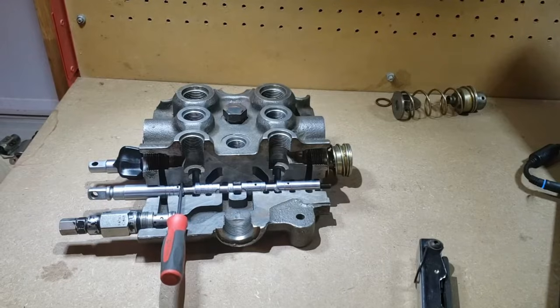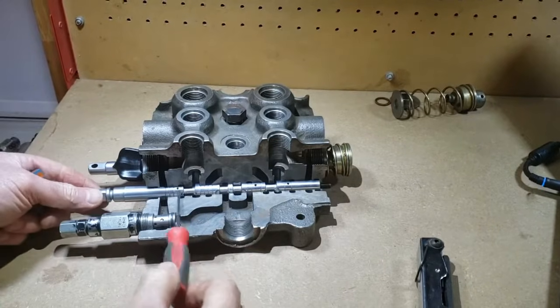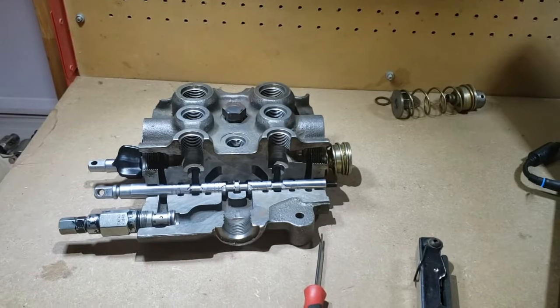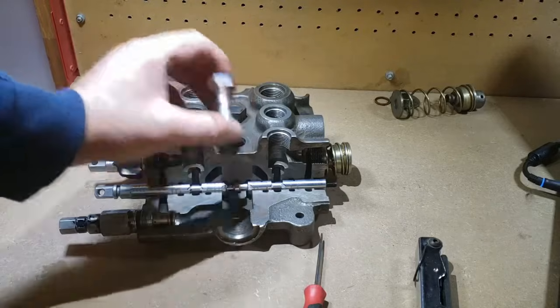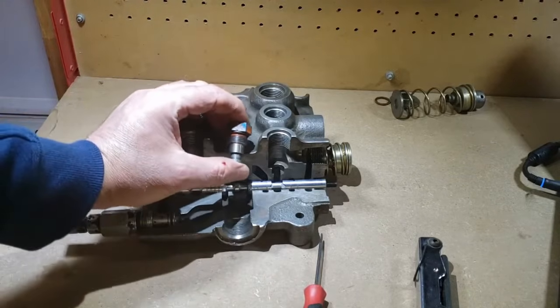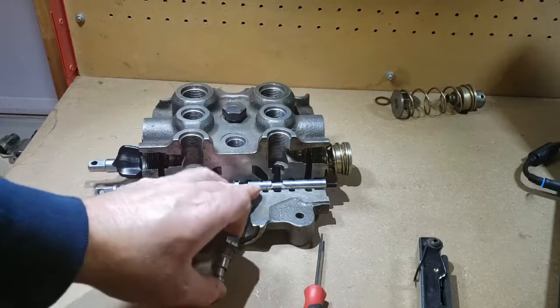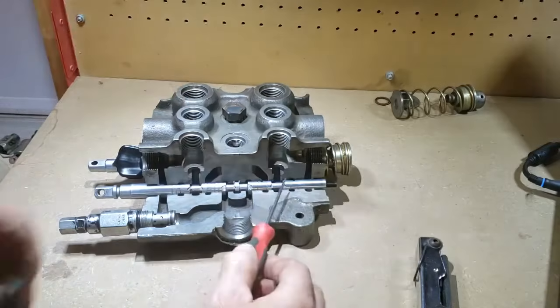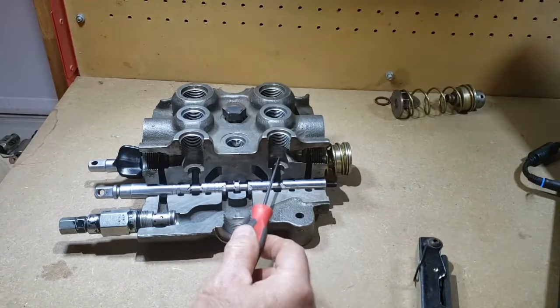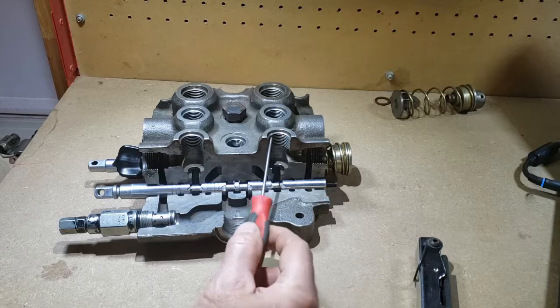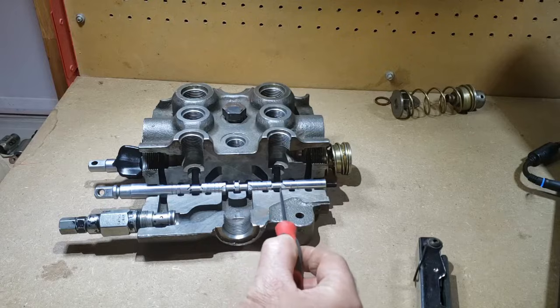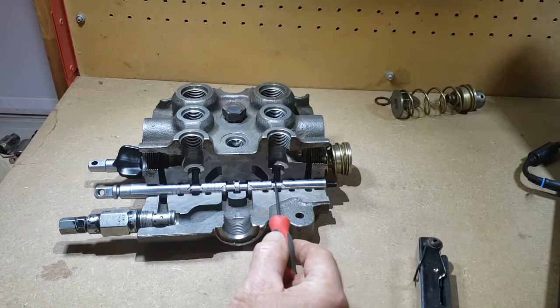Now let's talk about the load check while we're talking about that raise function. If the operator then puts the control valve back to the hold position, takes their foot off the pedal that operates the lift function, pedal operator on a base Bobcat, then the work ports will be blocked again. But if your loader frame is up in the air, you may very well have pressure in this work port. If you've got a load of material in the bucket and you're trapping that oil in the work port here, metal to metal clearances in the valve, I've sealed that off. You could have fairly high pressure here.